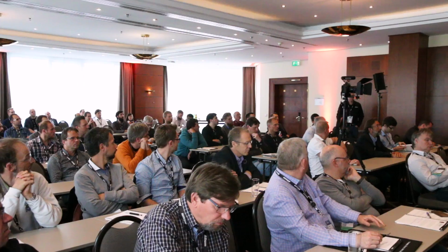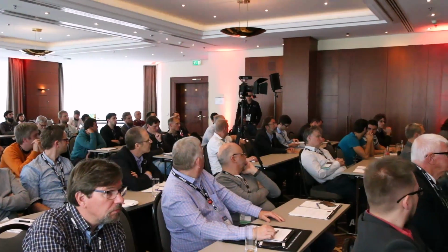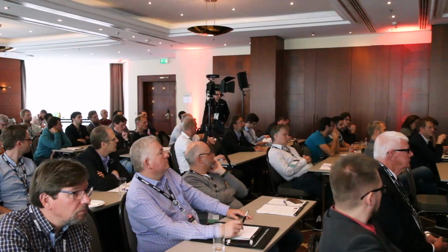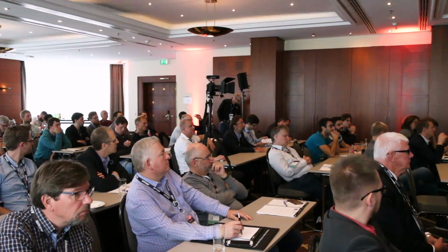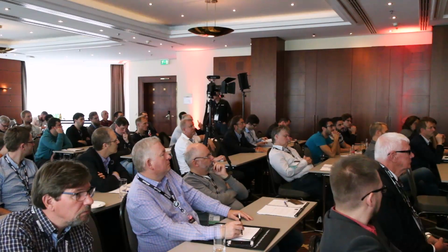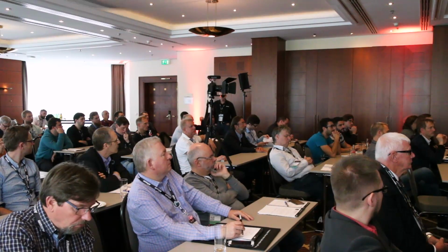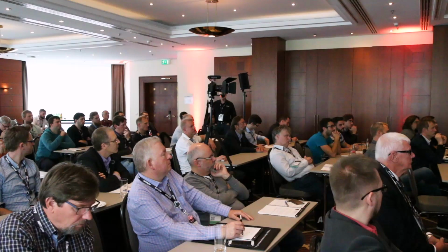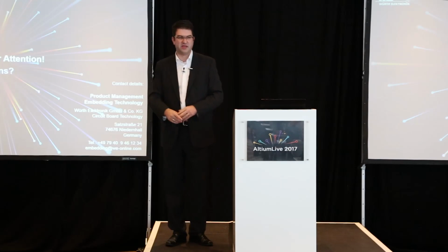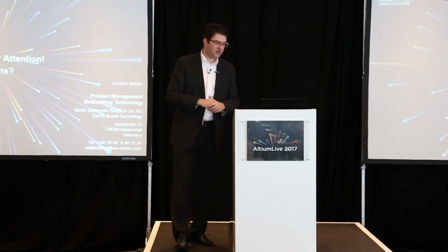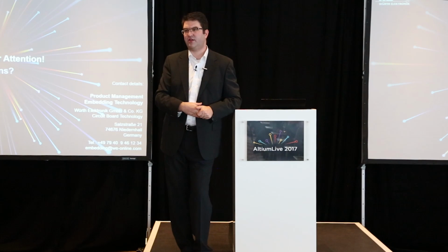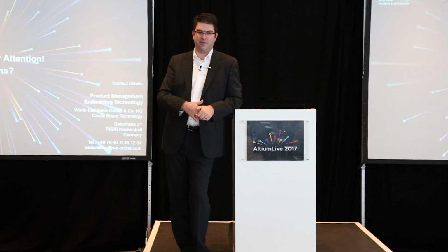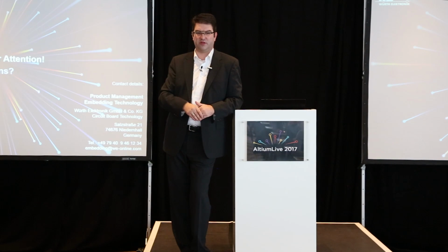When it comes to this microwire technology, is it also possible to connect on both layers, that you have, for example, a component embedded, connected from bottom and top? It depends. So yes, that's already being done. I didn't go into very much detail here, but for example, MOSFETs, when you have a backside connection needed, it depends on the die what you do. So there are several ways to get this done.